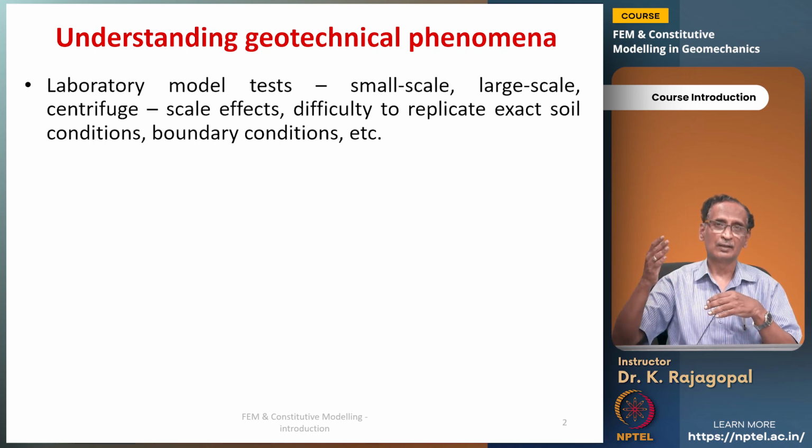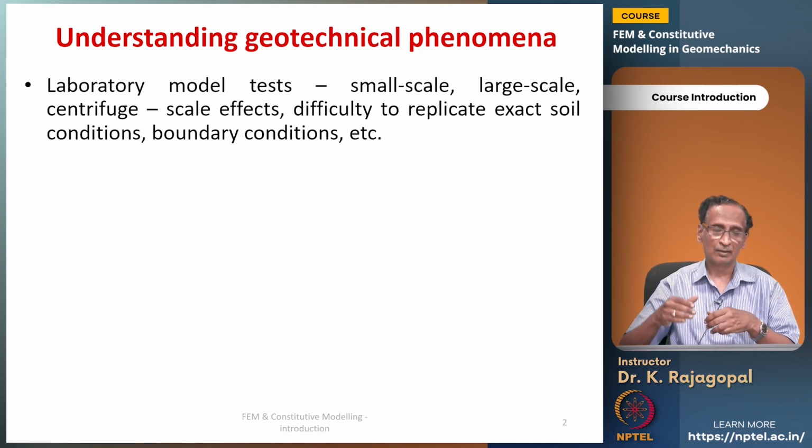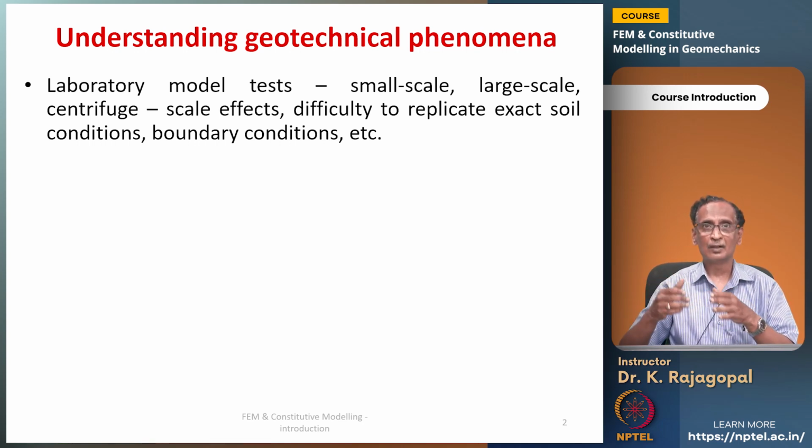Because of the difference in the stress levels, your soil in the lab may not perform similar to how it will perform in the field. So, we will have some problem in extrapolating. And then we may not be able to replicate the exact soil conditions that we come across in the field.